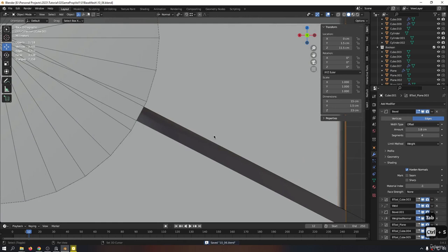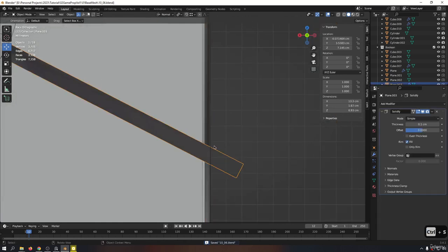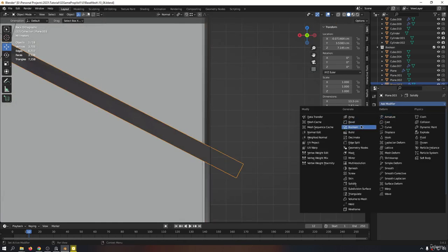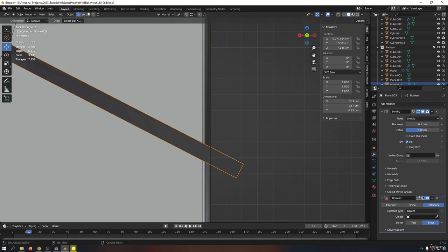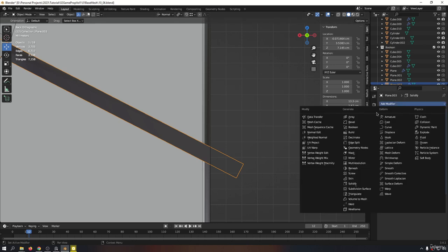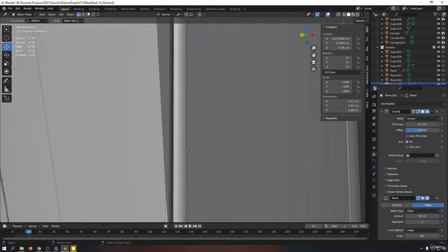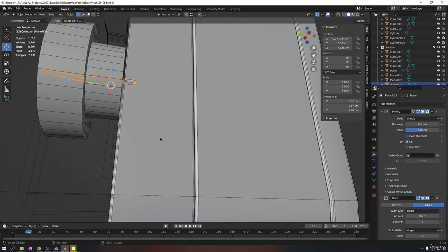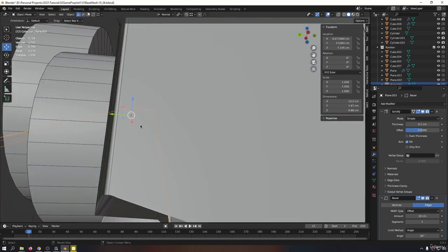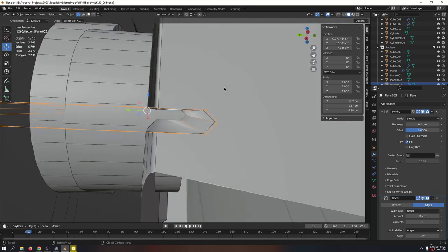And then I'm going to take this one, and in order to add more details to that, I'm going to bring in a bevel modifier. Excuse me, not a Boolean. Let's add a bevel. And this bevel is going to make these details a bit rounder and they get captured better inside the normal map. You see, this is with the bevel and this is without bevel.